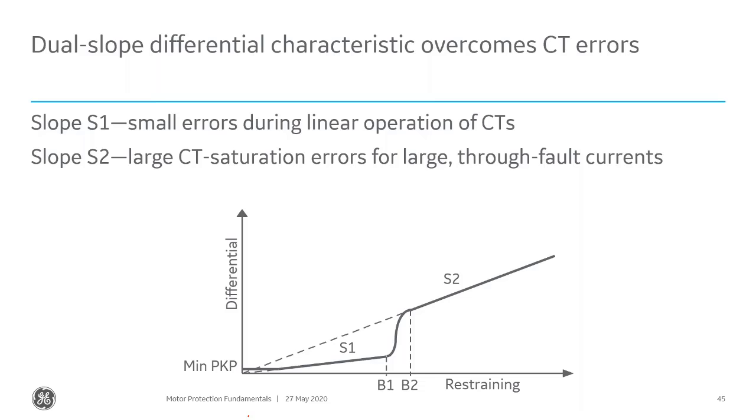What I mean by everything we can is we keep the phases separated inside of the machine. We might use isophase bus. There's lots of air between the phases. There's just that sort of small insulator between a phase and ground. So that makes a phase-to-phase fault less likely.